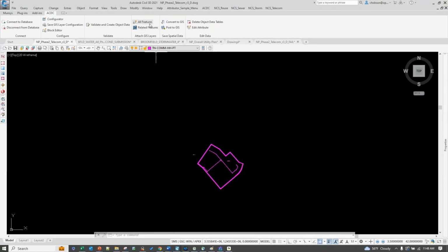You can then also go in and define and set up how you connect to your GIS. This off-the-shelf version is using FDO. We're also capable of pushing REST services straight into various GIS things. We can output into QGIS, you can output into SDE databases. From the portal, obviously there's a lowest common denominator that creates shapefiles, but you can also view that in a DWG viewer, which we will be loading straight out of that portal, and online if you have that option as well. So ArcGIS Online. I'll show you that in a minute.